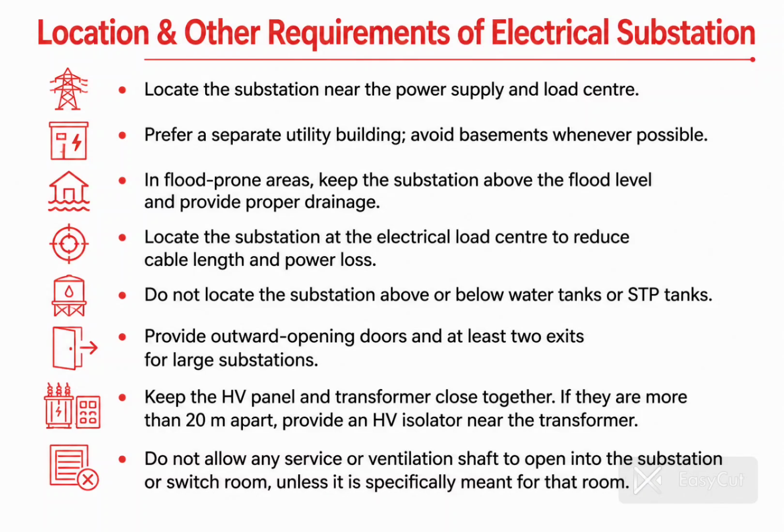Then the last point is do not allow any service or ventilation shaft to open into a substation. We should not take any other services, any plumbing services or any ventilation, any AC shaft, anything. Only electrical should be there in the substation. So we should not allow any other services to open into a substation. This is all about substation planning.